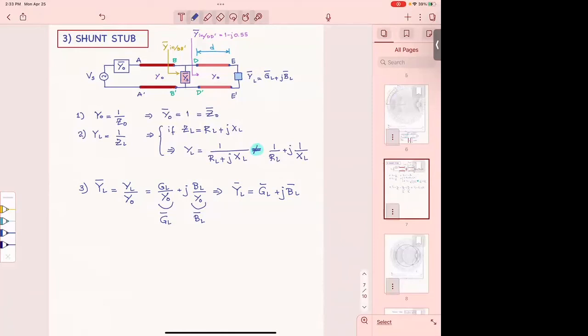For up today, I would say you will have to be very careful not to mix up normalized impedances with normalized admittances on the same Smith chart unless you transfer an impedance to admittances. And I will show you how to do it next time.